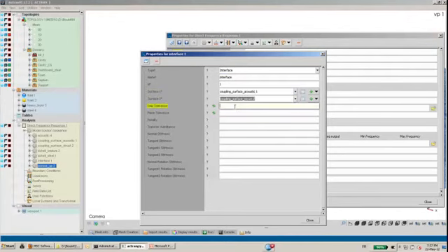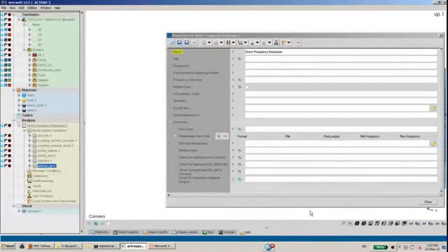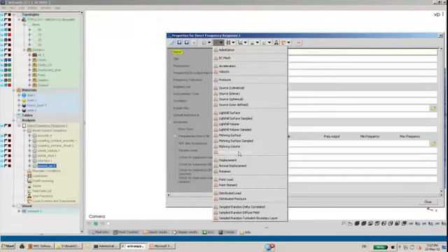Here we go. And I'm going to change here localization parameters because I have a small geometrical mismatch between the structure and the cavity. So I will say that I have a 10 centimeters allowance between the two. Okay, so when this is done, I have all the components needed for the analysis. But besides the components, I also need to create the boundary conditions. So there are two boundary conditions I need to create.